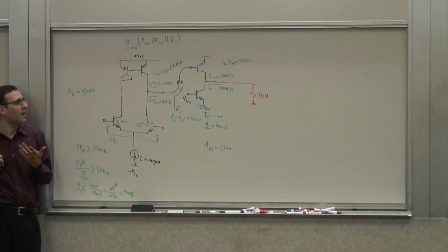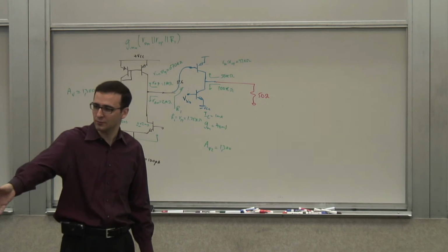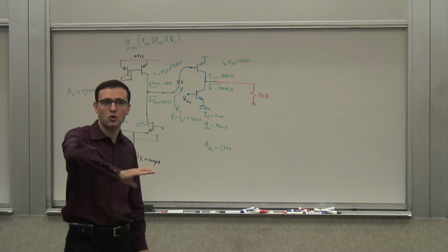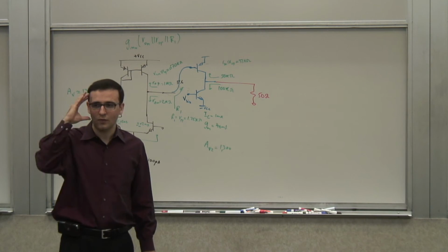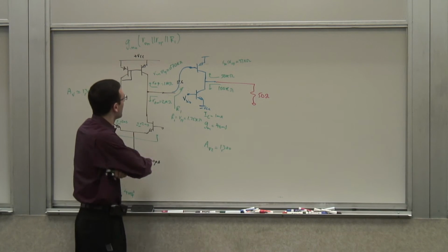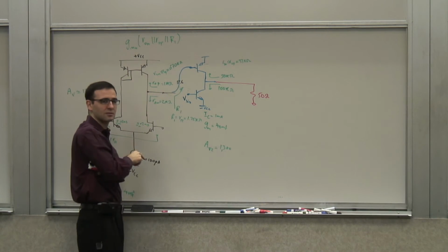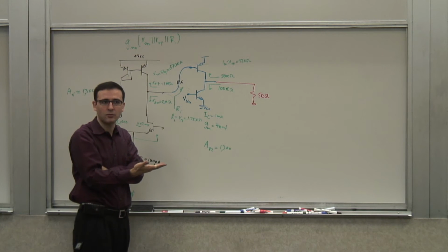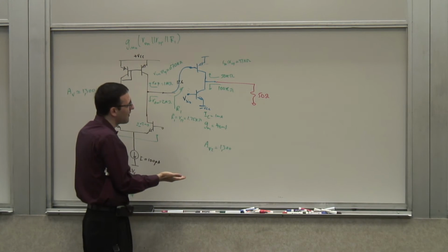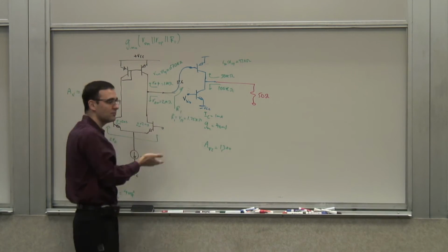So obviously I have a problem, but this is not a very bad problem, in the sense that I know I have a stage that gives me this impedance transformation, which is a common collector stage, which multiplies whatever impedance you put in its emitter by 1 plus beta. So every time you introduce one of those, you increase the impedance by a factor of practically beta. If I put one buffer stage here, the impedance I will see is beta times that. Beta is about 100, so I go from 1.25 kilo ohms to 120 kilo ohms, which is still much lower than 1 mega ohm and 2 mega ohm, but it's better.